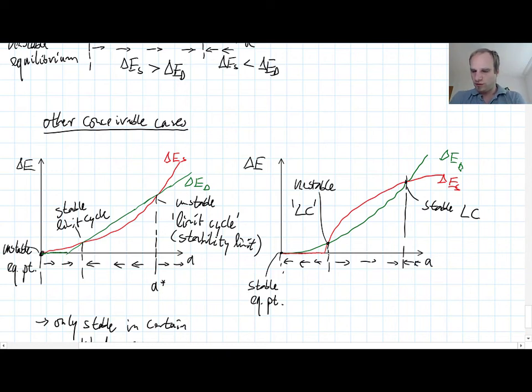Okay, because here amplitudes grow, here amplitudes decay again. So interestingly, the behavior would be for small amplitudes we remain in the stable equilibrium point or go again back to this. But as soon as we have amplitudes larger than this threshold here, then amplitudes grow until this point, until we reach this limit cycle.